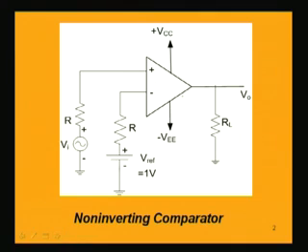Here the op-amp is having two voltages, as we can see here. The signal Vi is a sinusoidal signal, for example, we are taking, and this is time varying, that is taken at the positive terminal of the op-amp, and the constant reference voltage is 1 volt, which is taken in the negative terminal of the op-amp. Now, the resistance R is there for compensating the offset currents. So, we are having basically the comparing that is going on in this circuit.